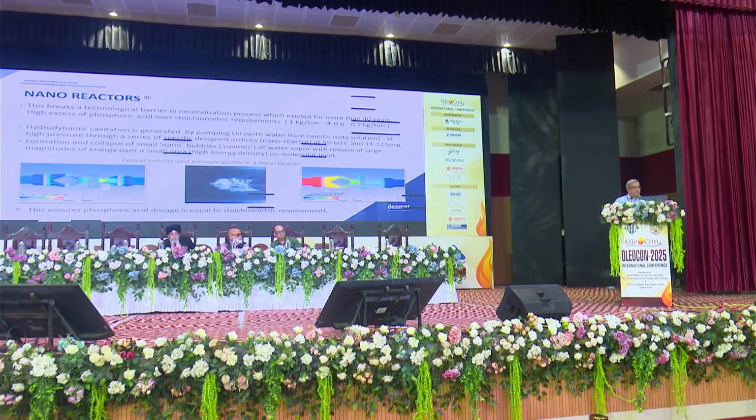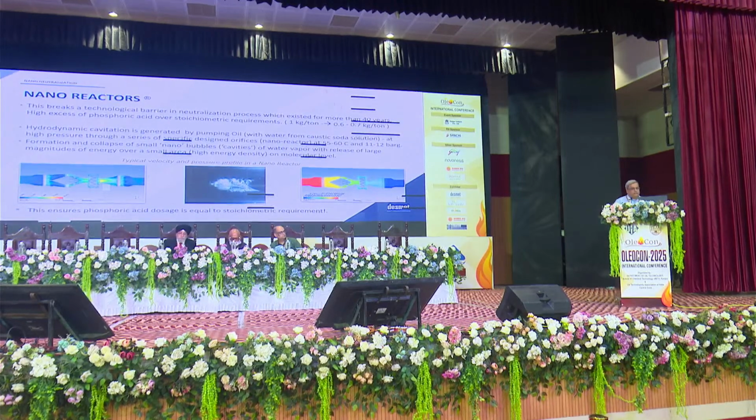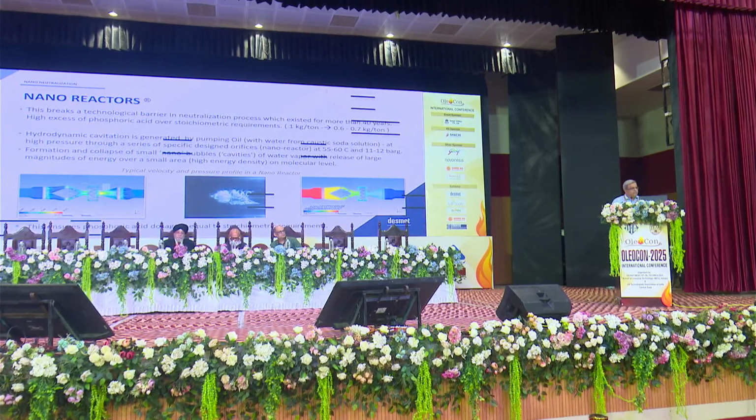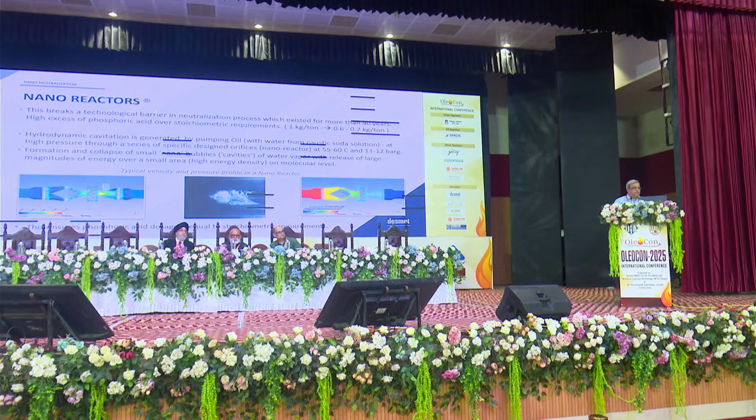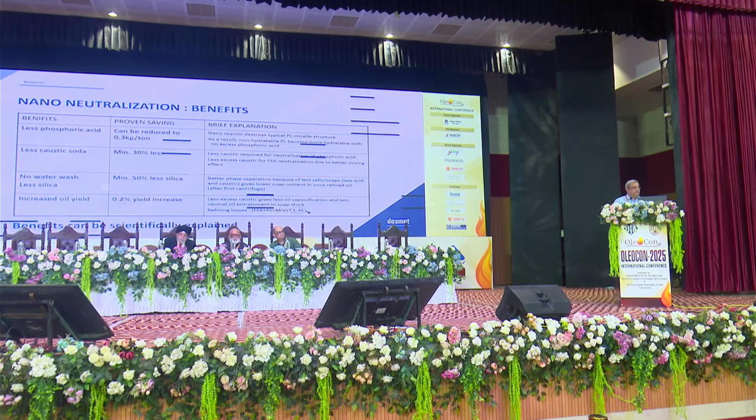It has actually broken a technical barrier in the neutralization process. For a long period of time we were using a high amount of phosphoric acid, much more than the stoichiometric requirement, and this has been reduced by the nano-cavitation. The energy released at the molecular level ensures that the phosphoric acid consumption can be reduced to the stoichiometric levels, and this itself then gives multiple benefits.